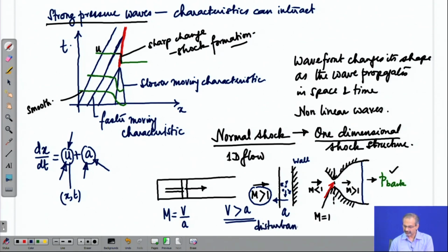So, what happens effectively is that though these molecular collisions are propagating upstream, trying to spread the information through these disturbances, they do not manage to go far upstream, because the incoming flow is higher than the sonic speed. The sonic speed is not sufficient for the disturbances to propagate far upstream, and therefore, at some point there is accumulation of disturbances forming the shock. And because of the geometric nature of the wall, the shock has a flat structure, which we call a normal shock.